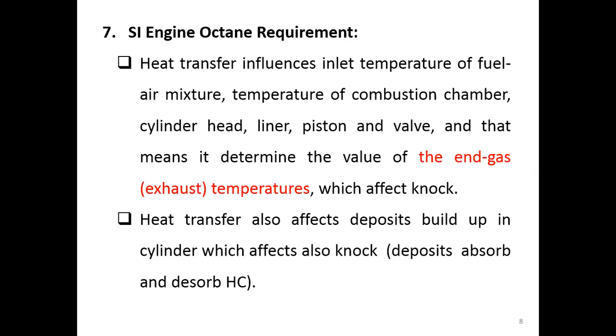And that means, since it influences all of this, it is the one that determines the value of the end-gas or the exhaust temperature. What should be the temperature of the exhaust gas? Because if the heat transfers to this, to that, to whatever, and does not concentrate on the combustion, the end-gas temperature will change.